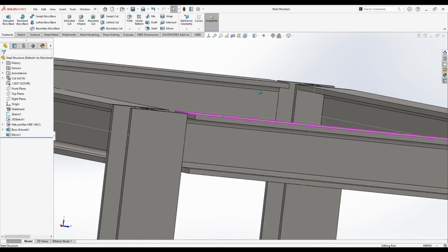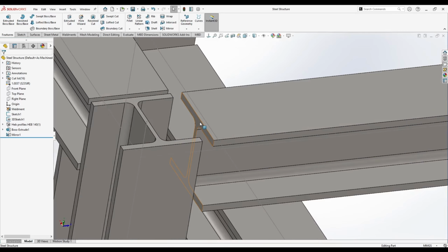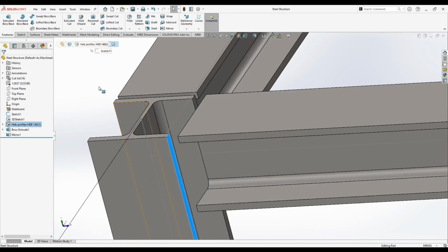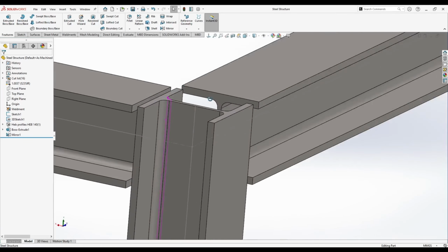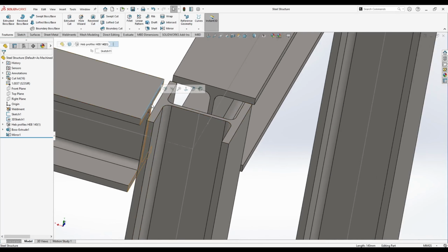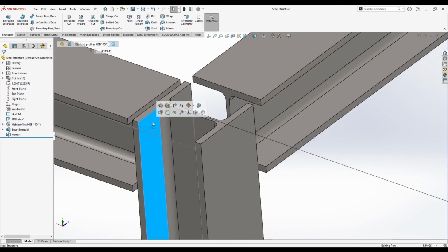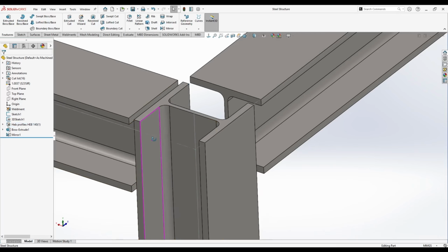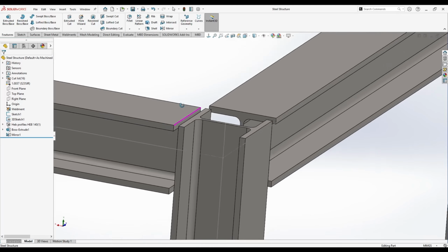Now we can add these small plates that will be welded. One to this profile, and another here. This is for this type of connection, and for the other one, we will have only 1 plate here welded to this profile. And we will drill some holes inside of these walls through which the balls will go.